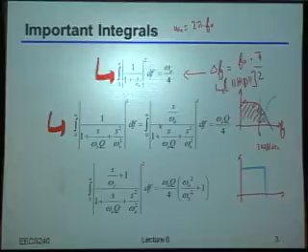The shortcut, once you've figured out a transfer function and you want to know that integration, is that it's essentially exactly the term in the denominator there, right? That's scaled by the s. If you just take the inverse of that and divide it by 4, that always gives you this integral here. Okay? So that's the shortcut for if you see this kind of transfer function, to immediately get to the integral.